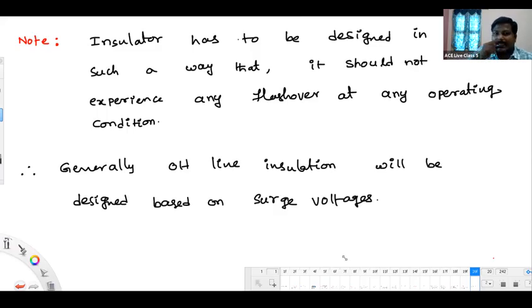A flashover and corona are not the same, Divya. Flashover is simply what we get after the insulator experiences that high stress: a flash. This is an arc between the conductor and the tower via the insulator. That we call flashover. So now I'm taking up the next slide.